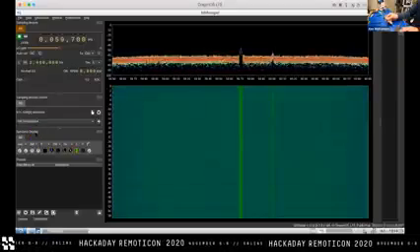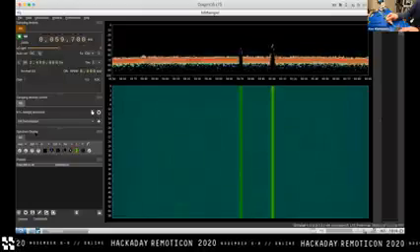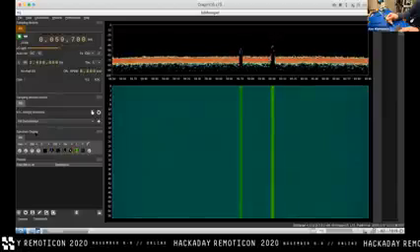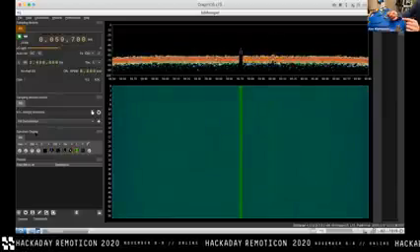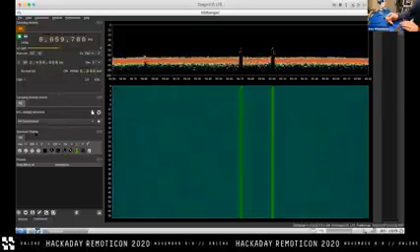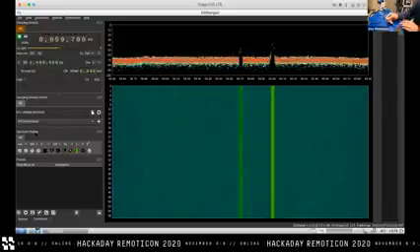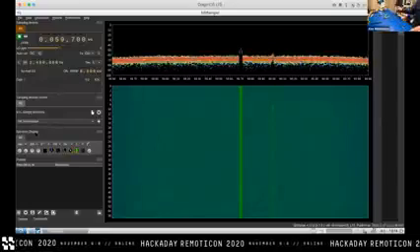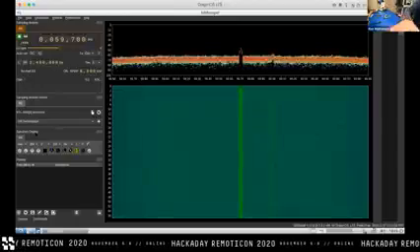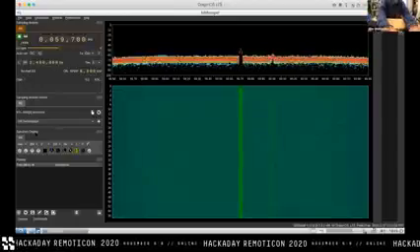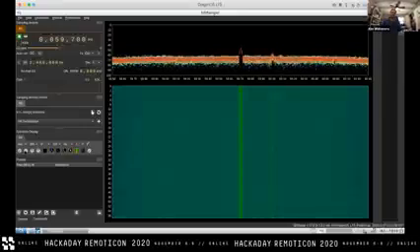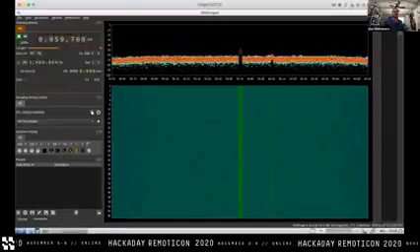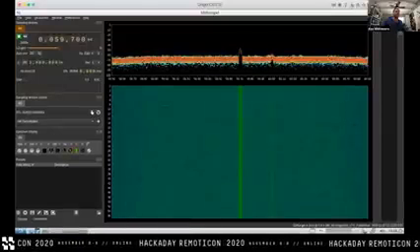Okay. Make that bin even a little bit wider. Okay, yeah. That's nice. So we've basically now built a tiny spatial resolution probe that can show us exactly which pin on the IC is radiating the noise in question. So let's go over and actually do this on the tiny FPGA side. My apologies that my tiny FPGA toolchain is on my actual Mac, so this might get a little bit ridiculous.